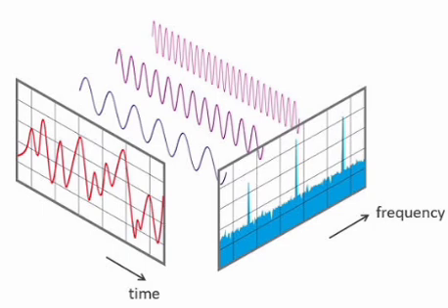Stability: an LTI system is stable if and only if the ROC of its system function H(z) includes the unit circle |z| = 1. A causal LTI system with a rational system function H(z) is stable if and only if all the poles of H(z) lie inside the unit circle, that is, they must all have magnitude smaller than 1.